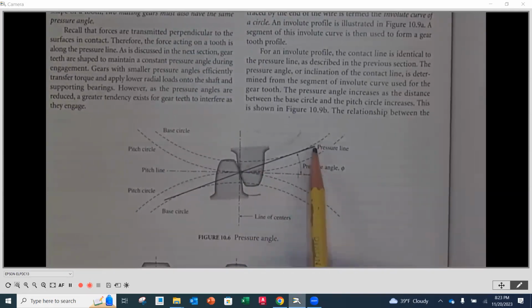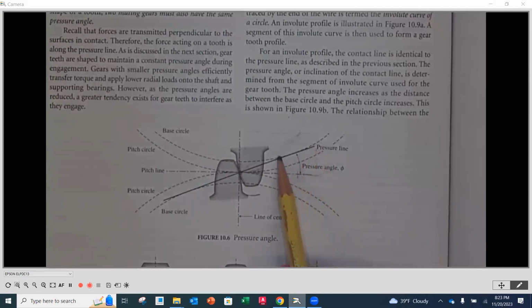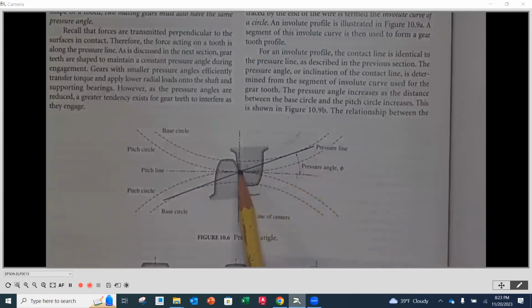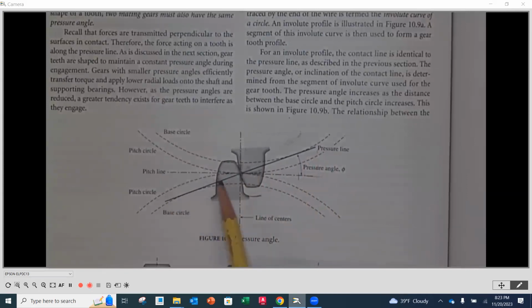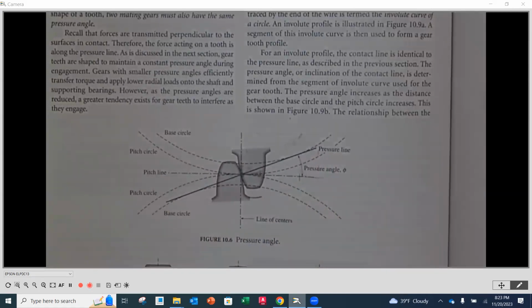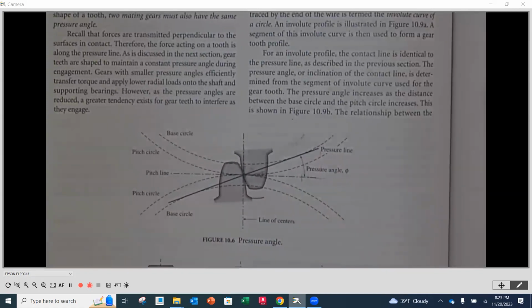That base circle line is going to go through the point of engagement, the pitch diameter, and it's going to be tangent to the other. This line with the horizontal makes what we call the pressure angle. Okay, it's where the resultant, and although in kinematics here we're not worrying about forces, we are transmitting forces here. There's 2 forces.